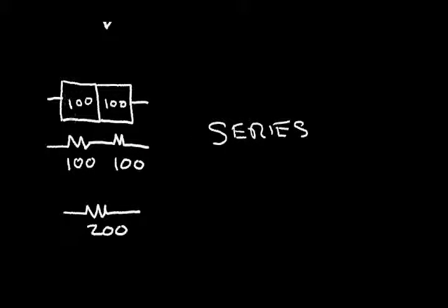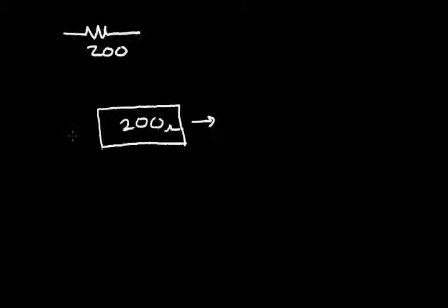So now I'm going to take the same resistor shape, these 2 squares of resistance, and I'm going to put that down here. So we know, since this is 2 squares, that this is equal to 200 ohms, and again the current is flowing in this direction. Now let's take the same material and double this dimension. We'll add another 200 ohm resistor here.